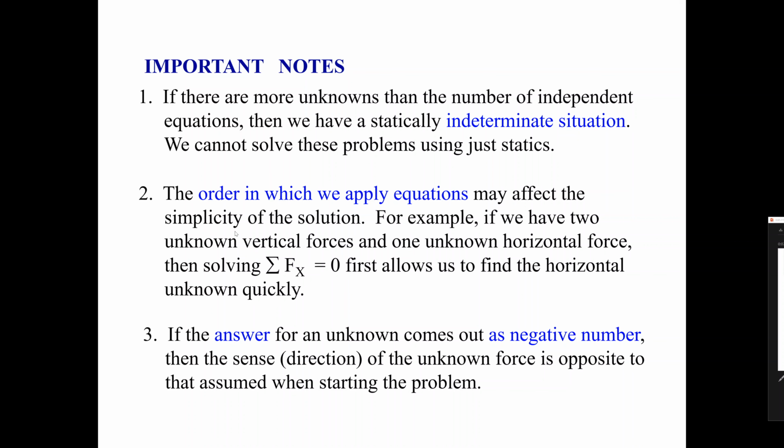Sometimes the ordering of how we solve a problem may simplify it. If you only have one unknown horizontal force and two unknown vertical forces, it might be quicker to just solve for the horizontal forces first, and then work from it that way.